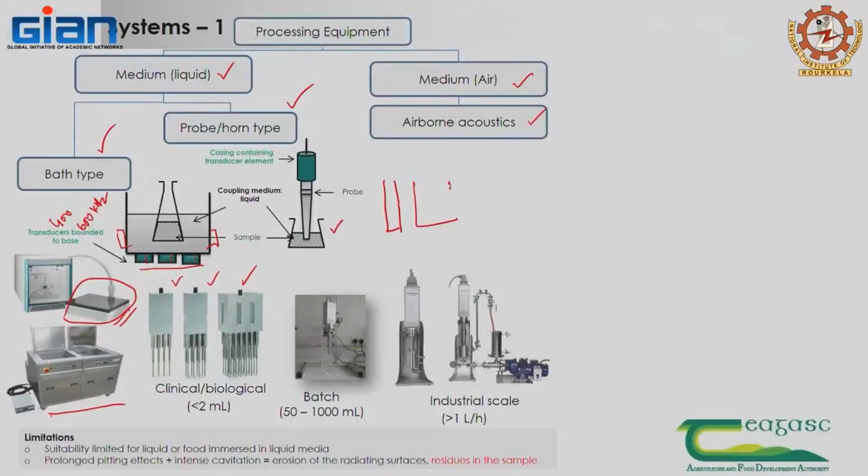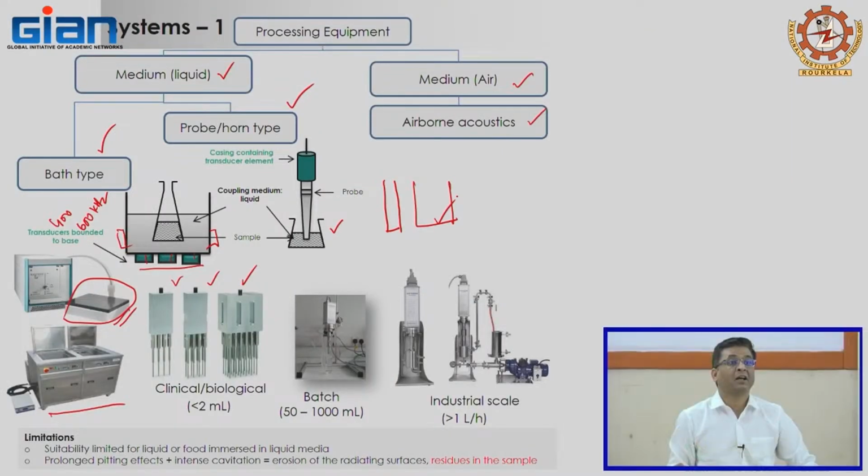So different size and length means they deliver different amplitude levels. In order to know the amplitude level, you have to go to the manufacturers. They only can tell you what is the amplitude of that machine. Measurement can be done, but again you need precise tools to do the micrometer measurement, right? So different diameter dictates how intensely you are delivering the ultrasonics. That is important here.